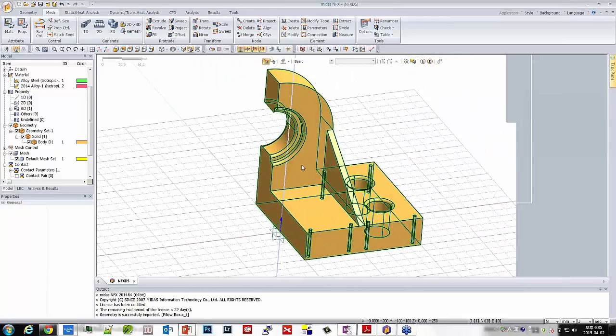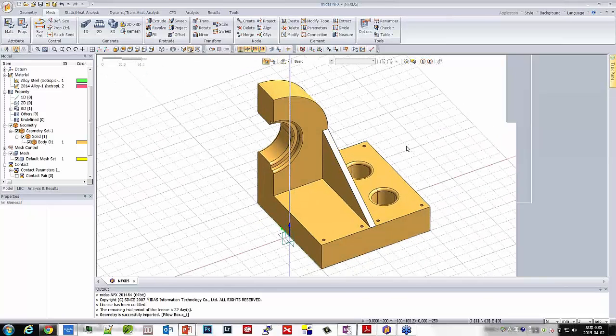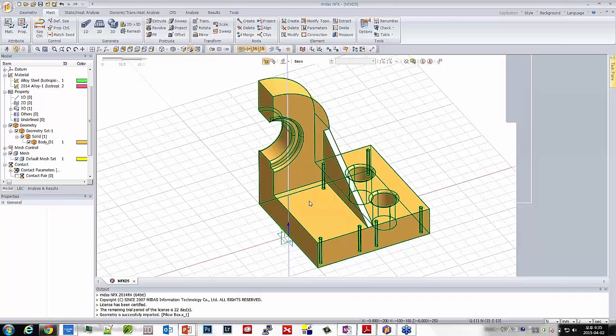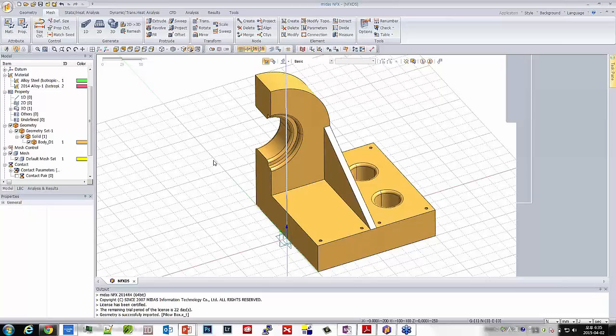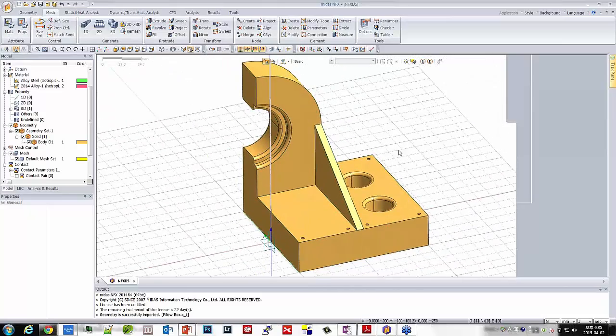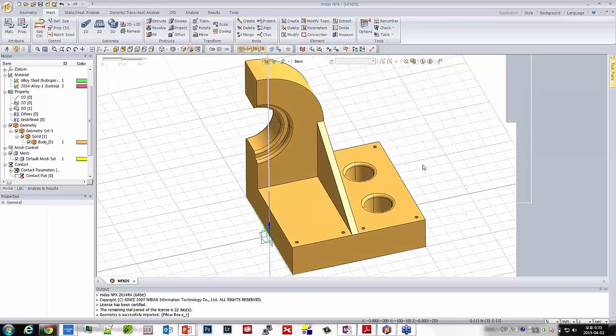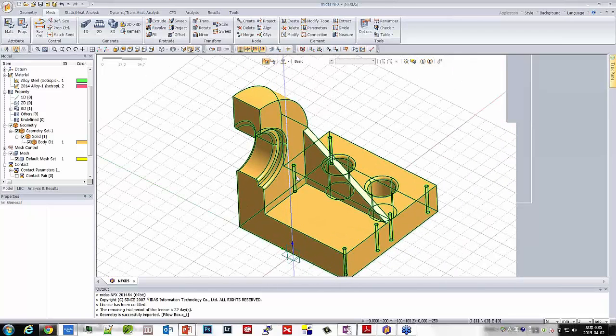Now, using this model, the first thing I'll do is simplify the model a bit. Usually when you're doing simulation, there are a lot of small details that you don't need inside your CAD model because they are not really bringing anything to your simulation, but they will complexify the analysis. Like, for example, these small holes or these fillets.